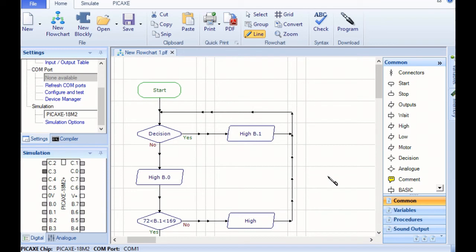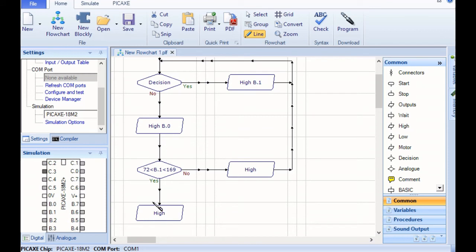Let's add a loop over there again, and now we've got a constant process of looping through in this fashion or in that fashion. Once the program is run through, this program doesn't know what to do right now, so I need to give it a task to complete or somewhere to go from there. So now this is an endless loop. No matter which state the inputs are going to be, it'll constantly run either through that branch or through that branch, but there will be no change in or no end to this program.